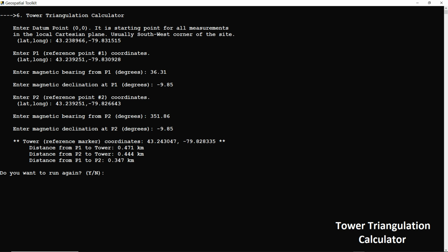For areas larger than 20 km radius, the curvature error becomes significant and can exceed practical construction tolerances without applying corrections. Therefore, for most construction applications, a maximum radius of about 50 km represents a practical upper limit for Cartesian plane triangulation, balancing accuracy requirements with the simplicity of plane calculations.